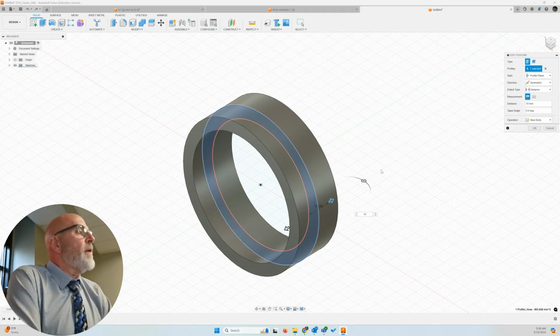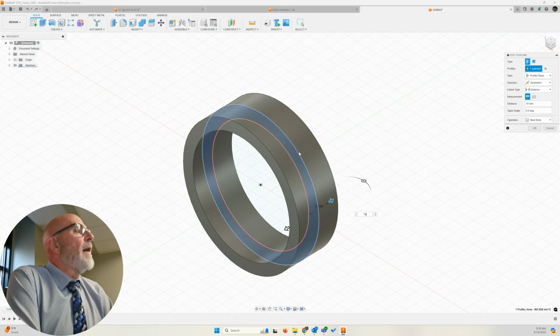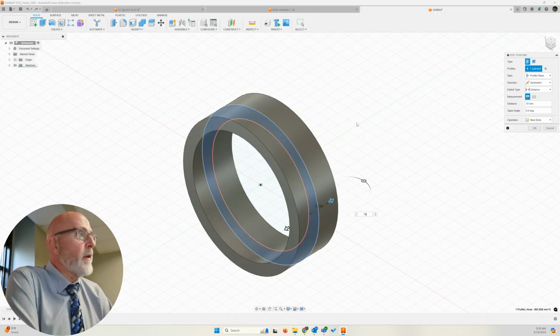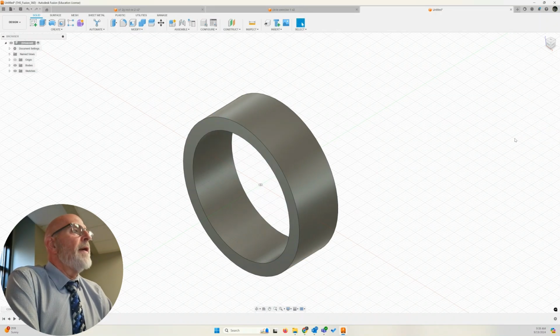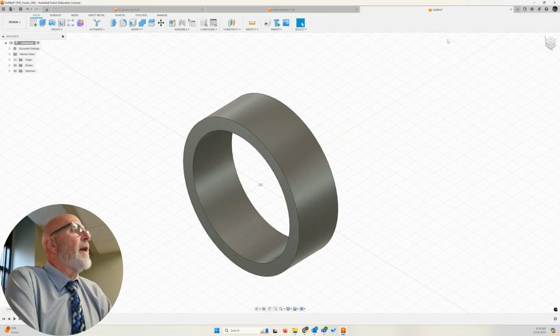All right, so what I've done, now here's my sketch that's on the front back plane. I have now gone 10 millimeters in both directions for a total of 20. Okay. Let's click OK. Now let's see what the change is when I go back. Let's re-add our construction plane.